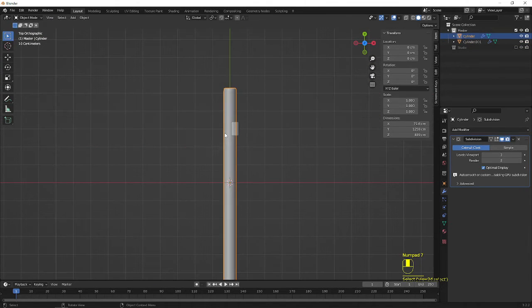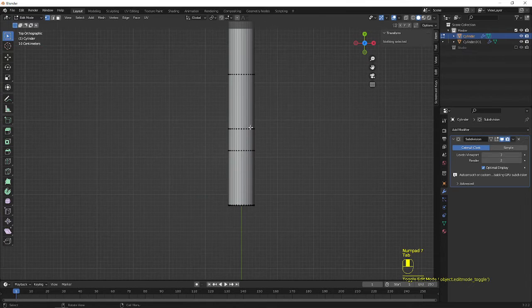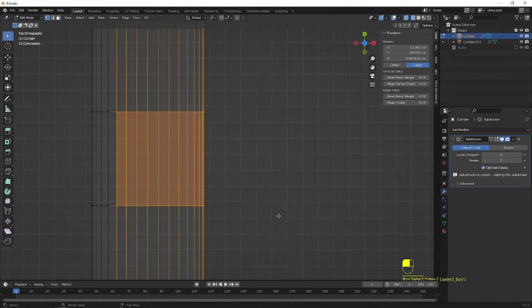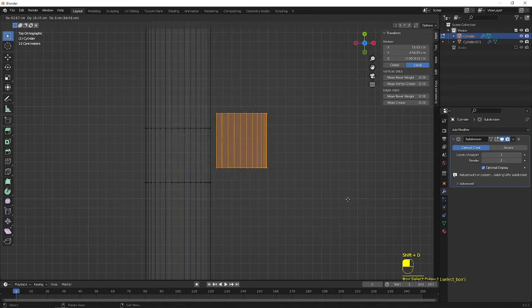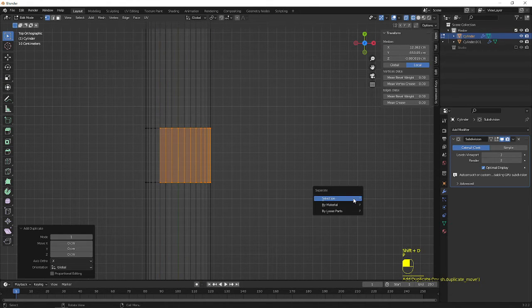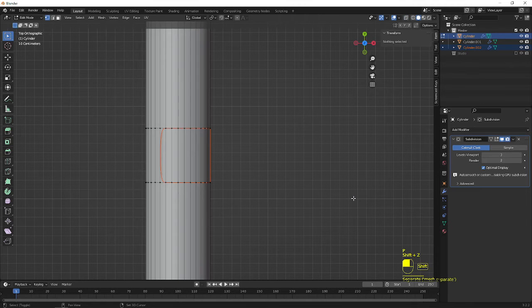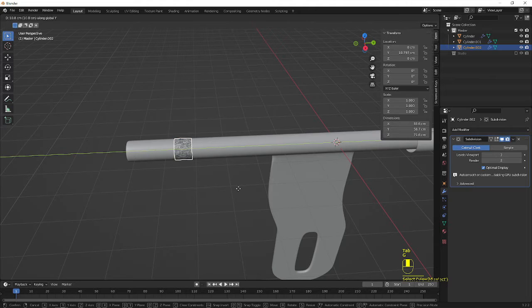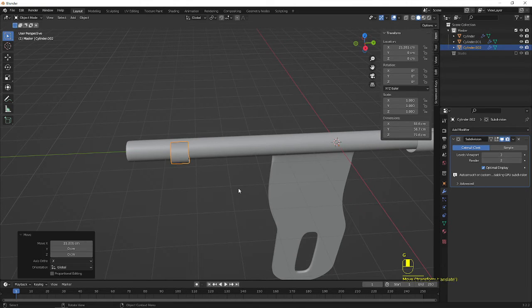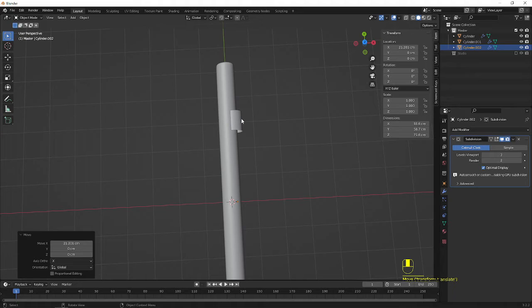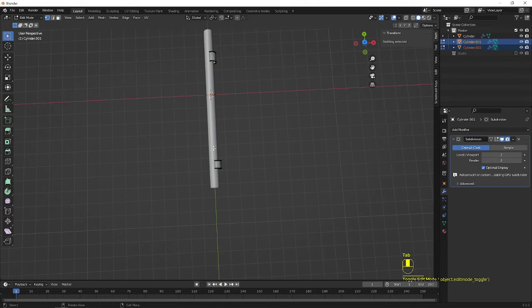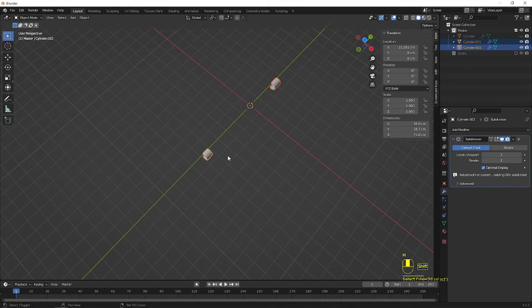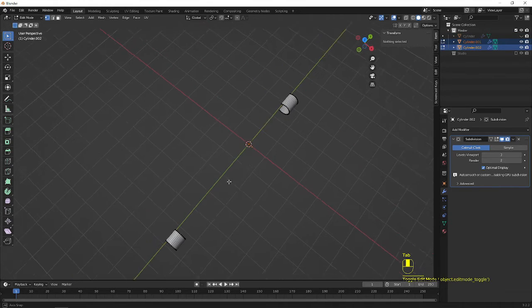The same way I am going to continue with this existing one. I am continuing the wireframe. I am going to select the required vertices, press Shift D to duplicate, right click to cancel, press P for the selection. Now I go to object mode. Now you can see the two things have been created. So now I select both and go to edit mode. Before that I select this handle and press H to hide it, for good visibility for us.